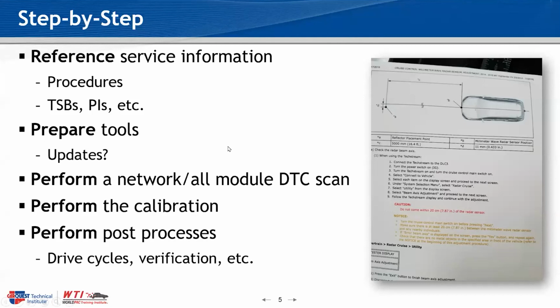That's an absolute yes, but I want to add just a touch to that if I can. Mechanics' logic, no offense, might say, well, if we lift the vehicle and we aim that radar or aim that camera down just a little bit, wouldn't that suffice? And the answer is no. The reason is that you have to consider the top portion of that visual window and the bottom portion of that visual window.